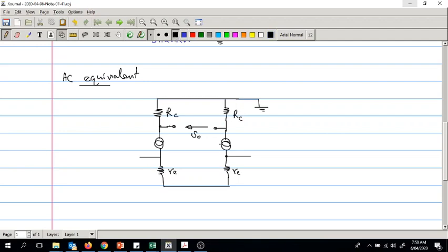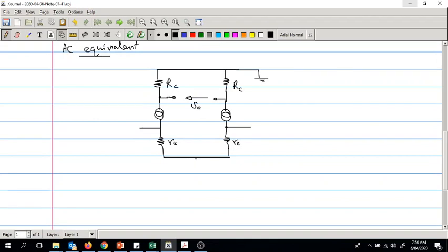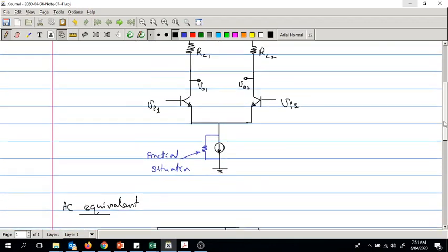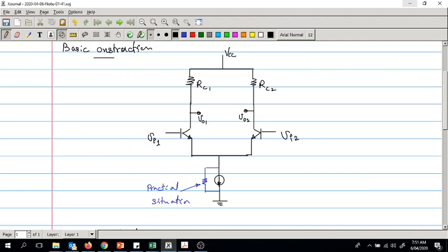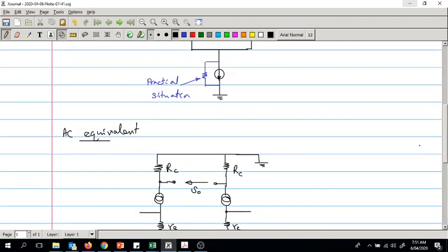We'll first draw the rest of the circuit. That resistor there will not go off in the case of AC, so resistors would be there. I replace the transistor of this circuit with the common base model, so we'll label that as using the CB model.